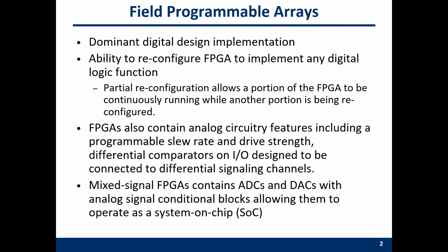For example, if you want to deploy a temperature sensor on your design, the sensing of the temperature is, of course, some analog signals. And then you can convert these signals into digital bits to see whether these bits are larger than some threshold value, and then to do something by the finite state machine we introduced in our previous class.